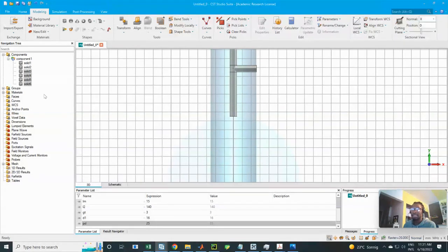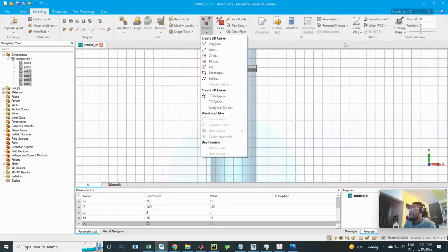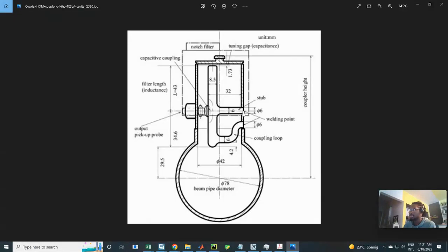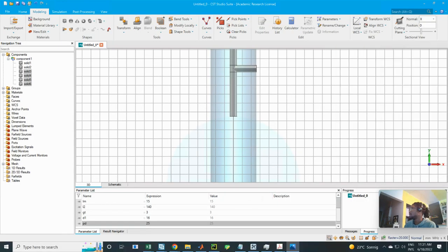So for this part, how do we approach this? I'm going to use curves. So we have a straight section. Okay, I'm just going to explain with the image. We have a straight section, then a bit of a semicircle curve this way, then another semicircle, no, quarter circle curve this one, quarter circle curve this way. Now the important thing is getting the dimensions right, and also parametrics, so that when you change the size of one parameter, it doesn't give you a degenerate geometry. It still gives you exactly the same thing, but scaled depending on the dimension you use.